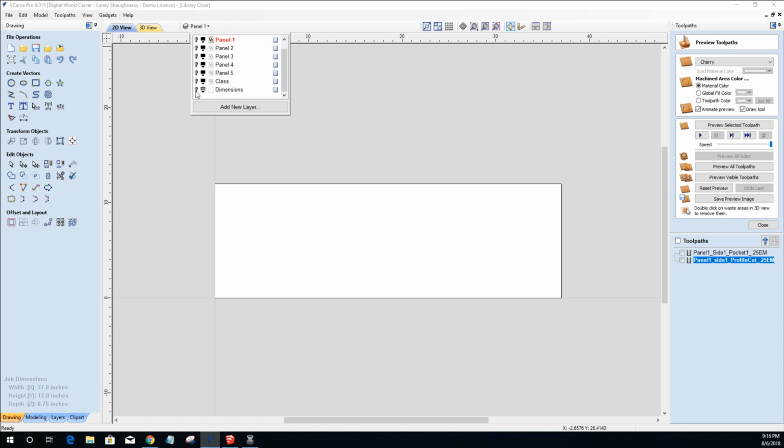The only hard part of it is the hinges, the cutting and kind of chiseling out, or using a handheld router. You could cut little hinge mortises with a little palm router if you had one, but you don't do those until you have the hinges. That way you can make the mortise match the hinge and everything.